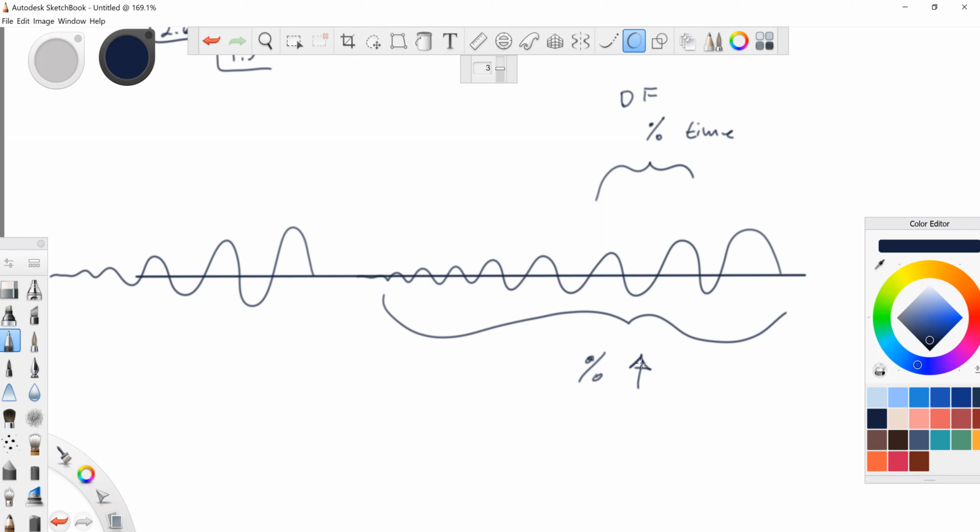No, that's exactly, this is pulse duration. It has gone up. It has gone up due to ineffective backing material. And if we have good backing material, then the pulse is short. 289, backing material decreases the quality factor. That is true.